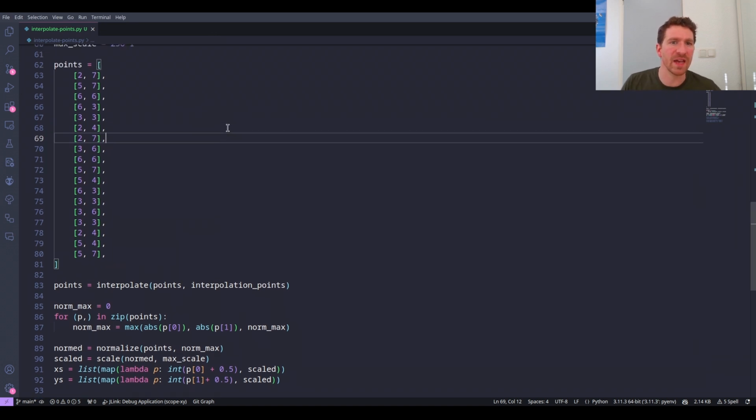And the reason that we do that is because in reality, when we put this through the low pass filter, when the oscilloscope is sampling and everything like that, you won't get this nice clean line drawing across. Instead, you'll get something a bit smushy, more smushed out by the low pass filter. So instead, we explicitly put in some of those in-between states in a really linear way, and that removes some of the noise that we have from the whole process, from the low pass filter and from everything else in the chain.